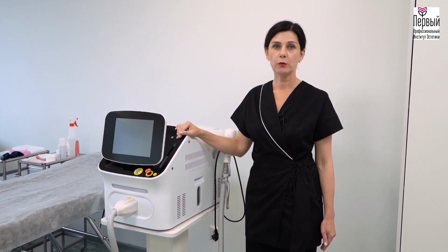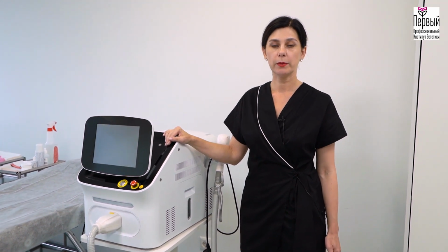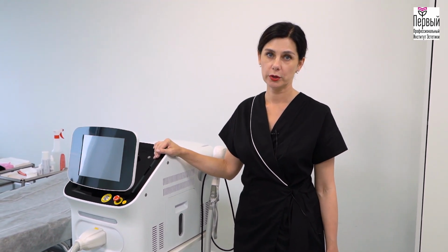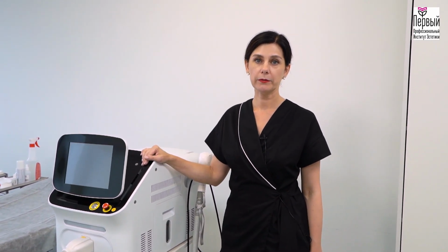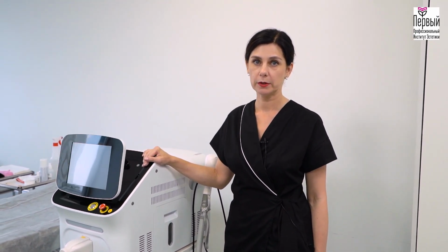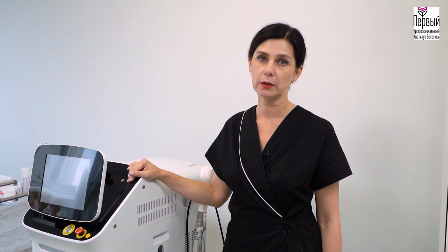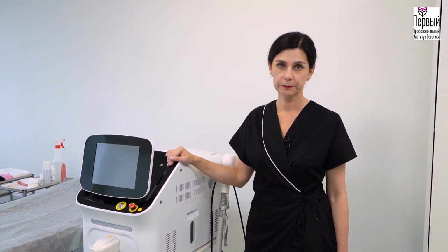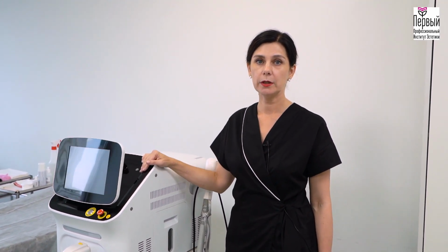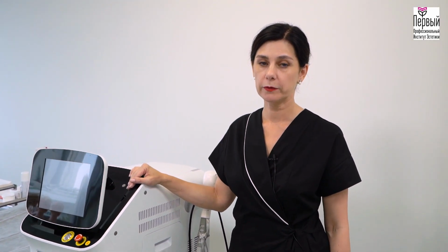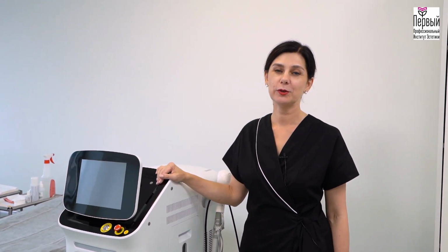The windows must be provided with shutters to avoid the direct sunlight. There must be no mirror or reflective surfaces within the operating field of the laser to prevent the laser beam from deflection. Light colors must be used for the floor, the walls, and the expendable items. Please use a non-conductive mat or wear rubber-soled shoes and keep a fire extinguisher in the room.